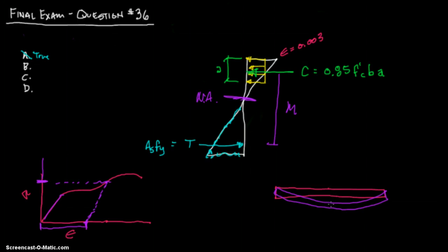and it will stay like that. You might remove that huge load. Let's say you have a pack of elephants go over your bridge, and you remove that load, and you say, oops, we failed. This is a failed bridge. We need to replace those. We overstressed it. That was a long way to go, but I hope you kind of caught on to what we were looking at there. So in the end, you want to overstress the steel. You do not want to overstress the concrete before you overstress the steel.